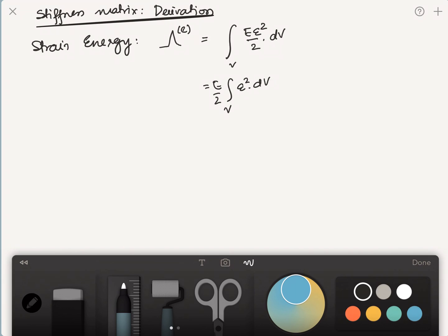Now it's important to derive therefore what the strain of the system is. To derive the strain of this system, let's get back to the elementary beam theory, the basic assumption that for any beam that is under bending, we'll assume a certain shape, somewhat like this. Goes better than my drawing, I hope. That if this face is AB, then this face is also AB and it remains straight.